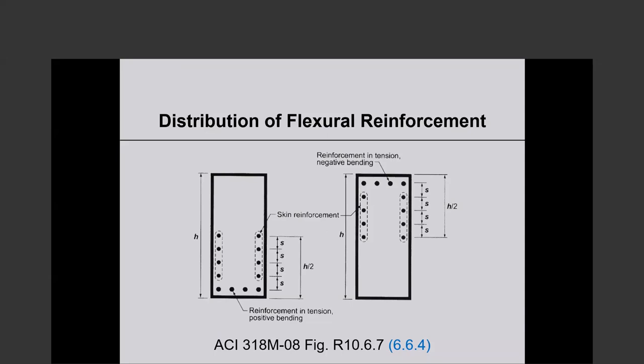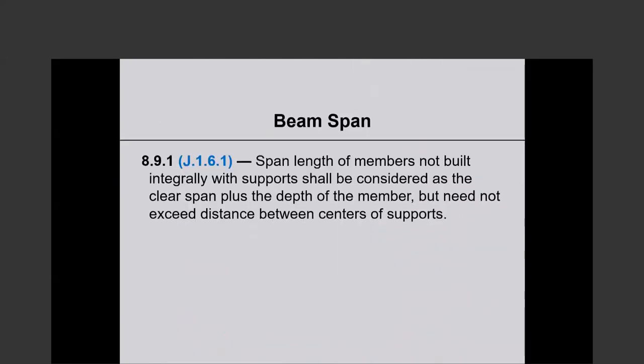Okay, once we got into design, we talked about maximum reinforcement ratio, minimum reinforcement ratio, crack control through imposing maximum spacing on the extreme tension reinforcement, and now skin reinforcement, which is for deep beams only, depth exceeding 900 millimeters.